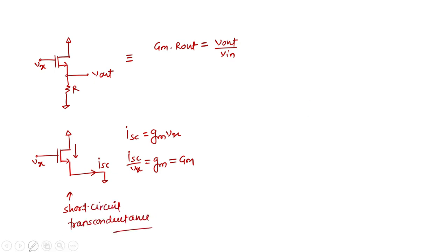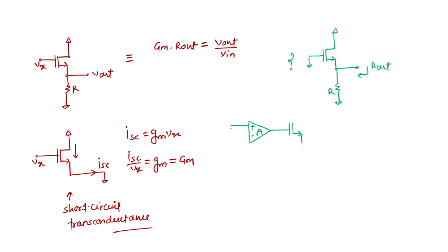Now we will look at the calculation of R out. So now the point is, is this exactly the correct way to calculate this? What should I say for R out, or should there be something on this gate? This is the point. Because what was previously connected here? If I am calculating the R out, what is connected here? This gain block is here. And here let this voltage be 0 first, so I cannot directly calculate the output impedance of this MOS.